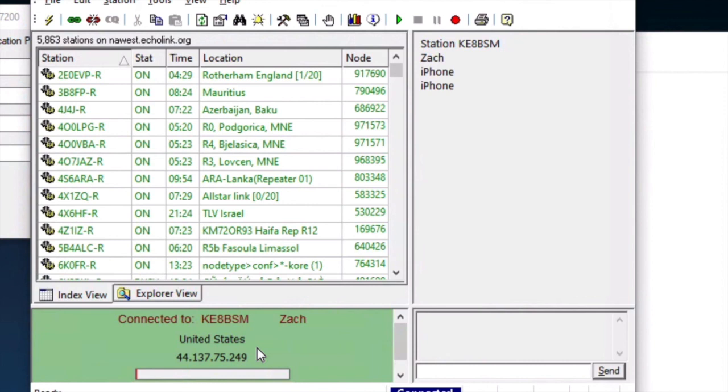So that is why menu item 55 on your ICOM IC-9100, having USB audio squelch turned on, is important, and that was where I was getting hung up. Menu item 55 is what hung me up for 3 or 4 years.